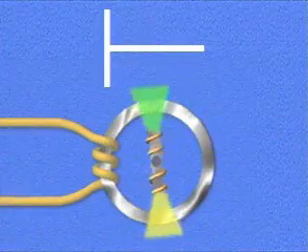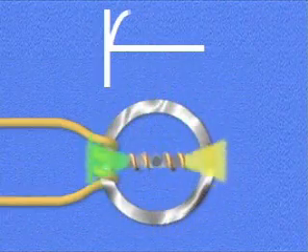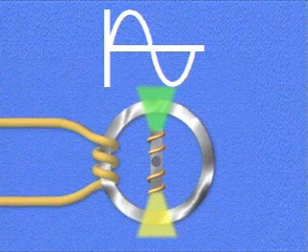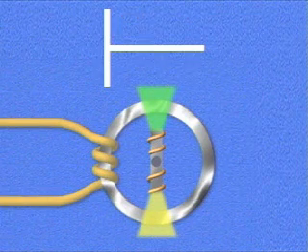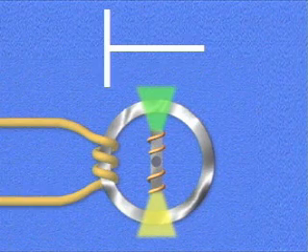As the electromagnet rotates, the relative positions of the electromagnet and the conductor affect generator output as shown on the graph. When the electromagnet is vertical and the magnetic fields don't cross the conductor, the voltage is zero.